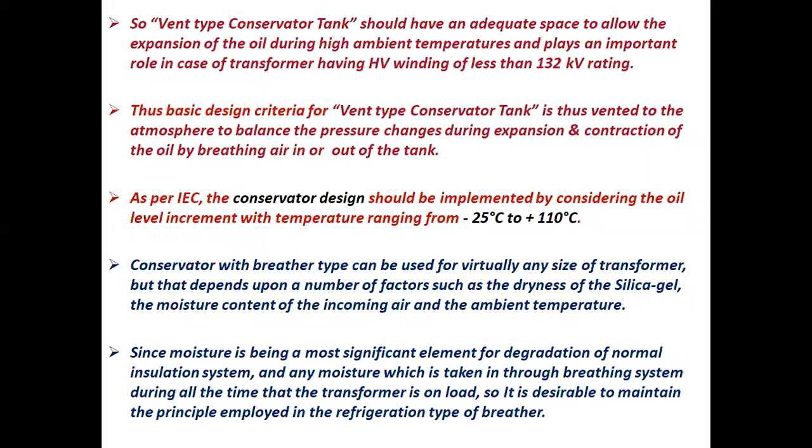So, a vent type conservator tank should have adequate space to allow the expansion of the oil during high ambient temperatures, and it plays an important role in transformers having an HV winding of less than 132 kV rating.